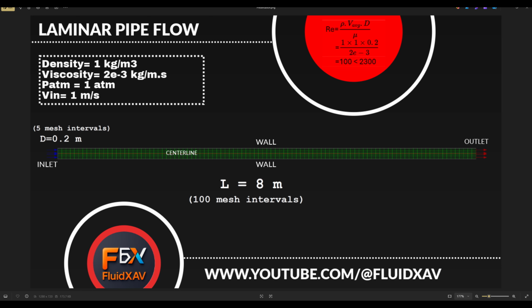We will work in axisymmetric mode, which means we only model half of the cross section to save computational time. The pipe length is 8 meters, and since we are modeling the radius, the height of our 2D geometry is 0.1 meter, corresponding to a full pipe diameter of 0.2 meters. The inlet velocity is 1 meter per second.